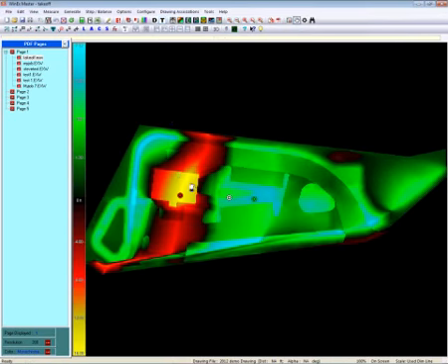I want you to notice these circles. These are the centers of mass. This is our cut and fill map. This is the center of mass where you want to place your equipment for most efficient use during the cut, and this for the fill. Notice under my wrist where the hand is, it says distance NA, but if you click anywhere on the site, like here, and then move the hand away, go back to that window, and you'll see the distance on how far you've moved the hand from that first click. So it gives you a pretty good perspective of distances on the site.